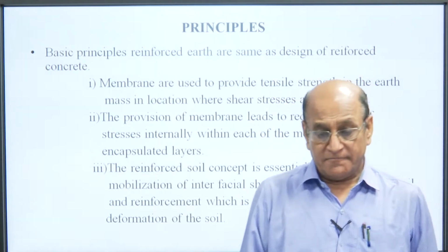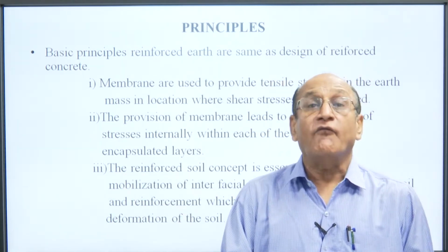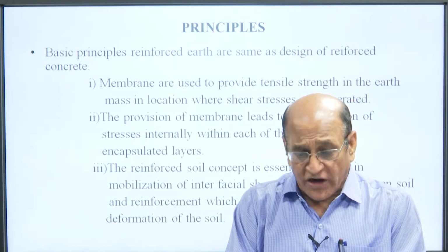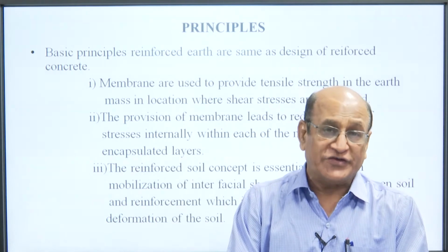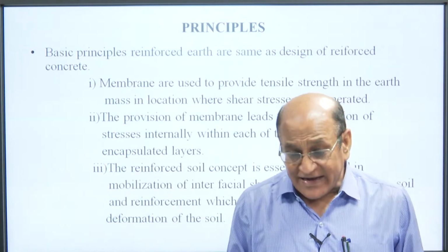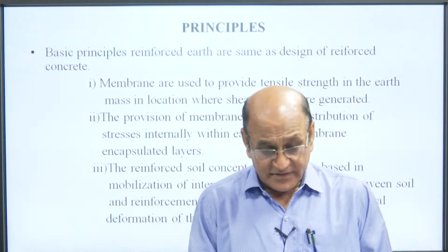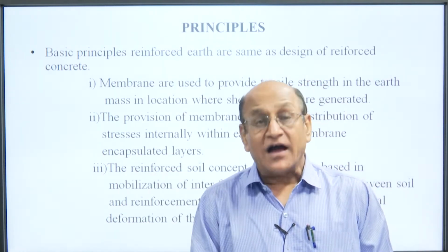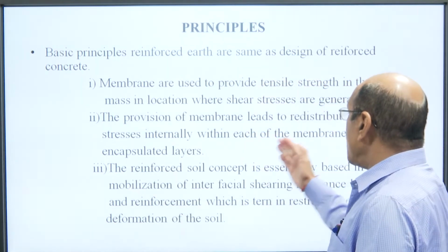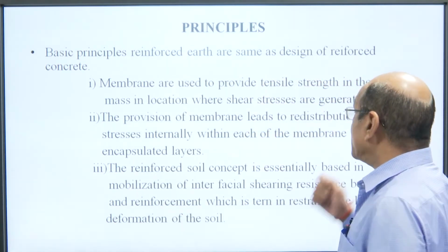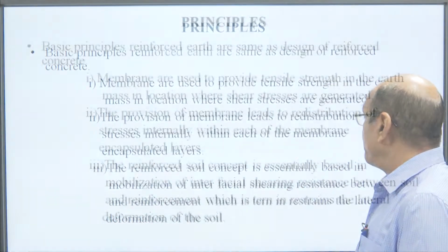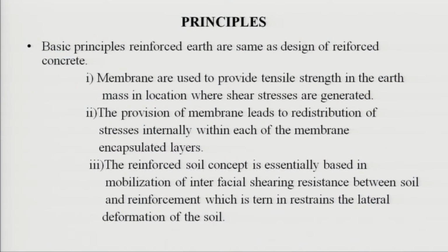The principle by which reinforced earth works. The basic principle of reinforced earth is the same as the design of reinforced concrete. Membranes are used to provide tensile strength in the earth mass in locations where shear stresses are generated. The provision of membrane leads to redistribution of stresses internally within each of the members in encapsulated layers.